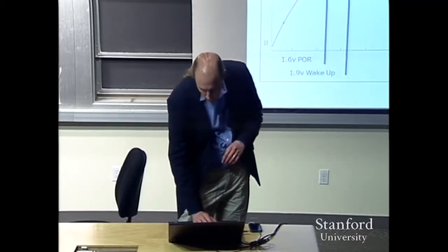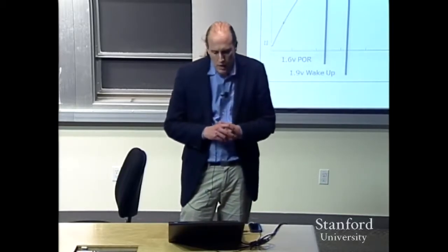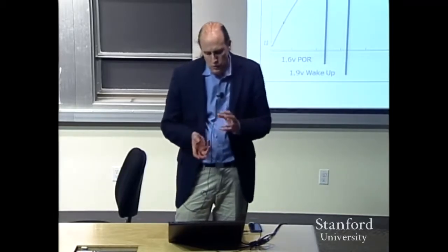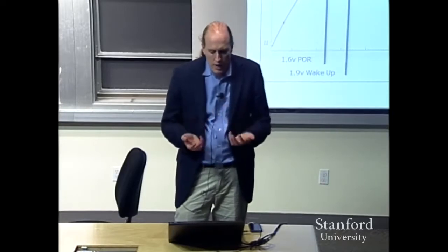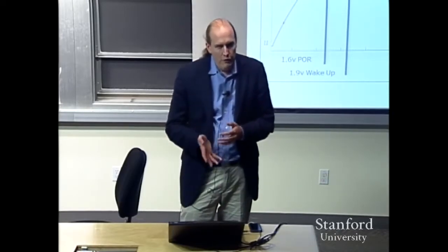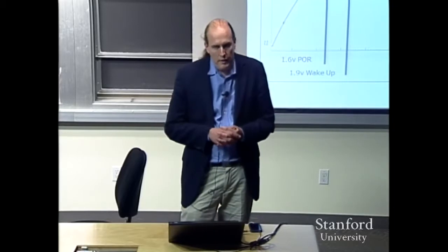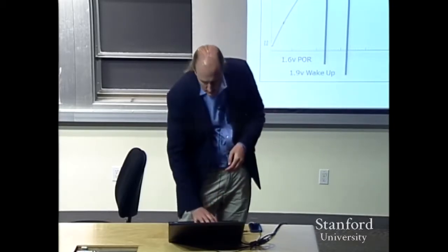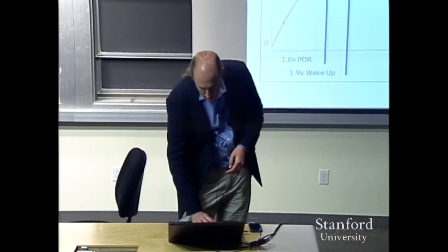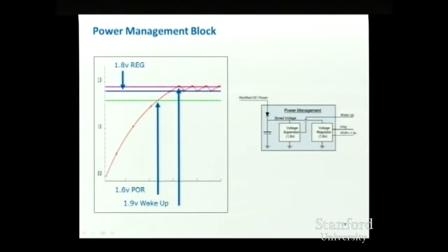Now, one of the things a lot of people are working on now is more sophisticated schemes that use software, because the size of the job you're executing can affect the way you want to do this duty cycling. If I have a job that takes longer to execute than the time I have available here, I may not be able to finish before the tag goes to sleep. So various ways of doing adaptive thresholds is something that many of my colleagues are interested in now.